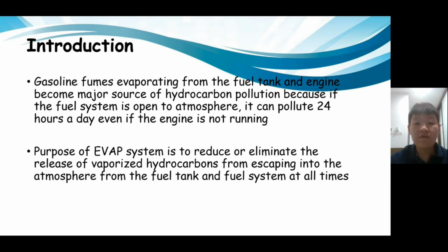Gasoline fuel evaporated from the fuel tank and engine becomes a major source of hydrocarbon pollution, because if the fuel system is open to the atmosphere, it can pollute 24 hours a day even if the engine is not running. The purpose of the EVAP system is to reduce or eliminate the release of vaporized hydrocarbons from escaping into the atmosphere from the fuel tank and fuel system at all times.